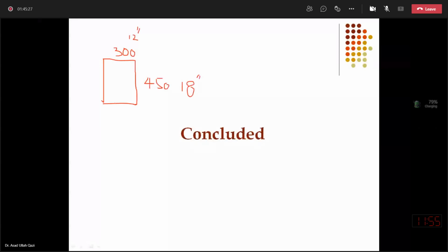And it is reinforced with 3 bars of dia number 25. Number 25 bars, if they are US customary bars, you can check them in design aids in tables. US customary bars. Number 25 has the nominal area 510 millimeters square.